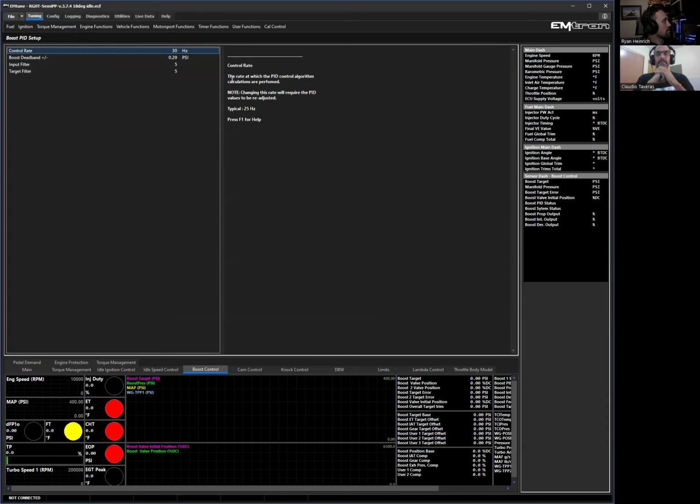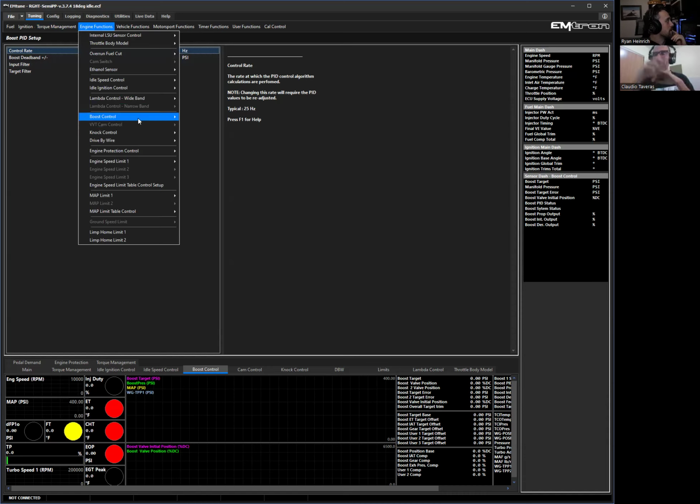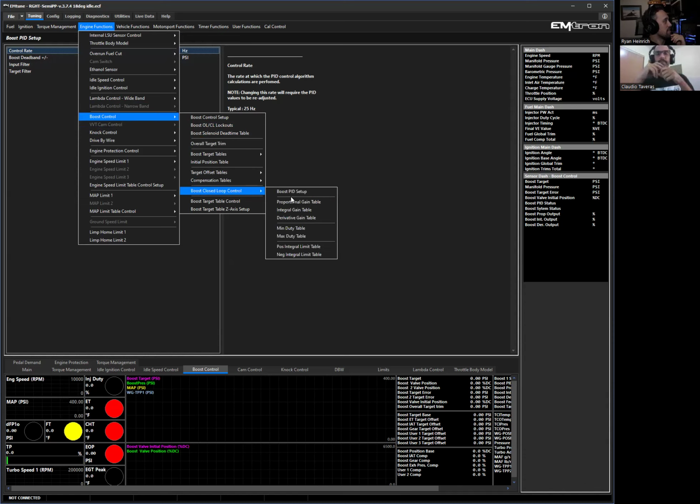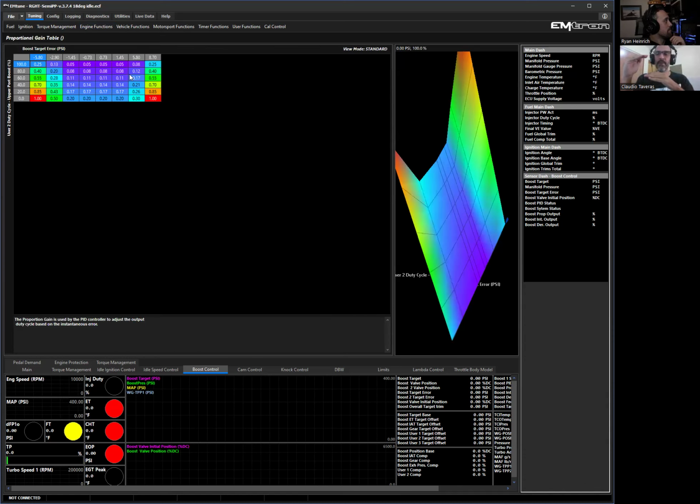First off, frequency, and then it's got a deadband of 0.3 psi before it even touches anything. So if it's not within that 0.3, it'll enable. If it's within 0.3, it will use that feed forward table, the initial lookup table, exactly as it is. Is it a plus or minus, or is it a below? It is plus or minus. So you're basically giving it a window of operation above or below target. Correct. And so we've got on this one.